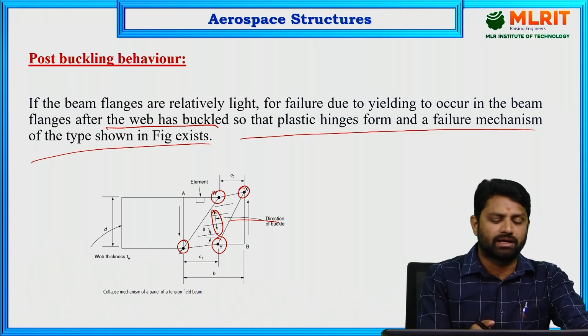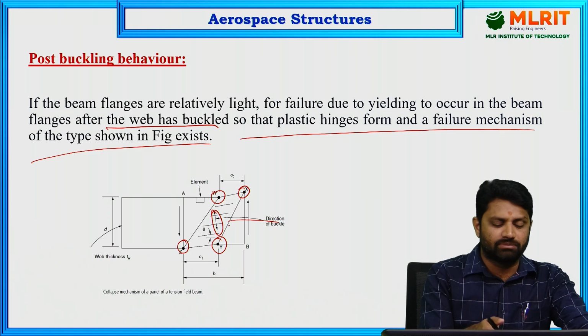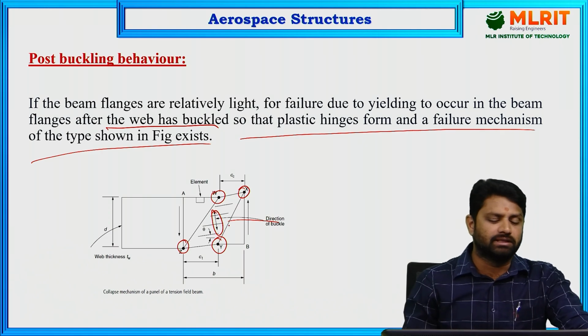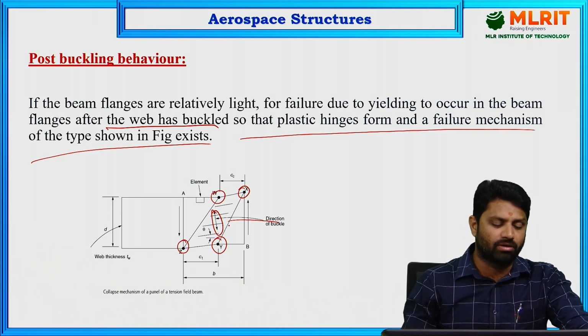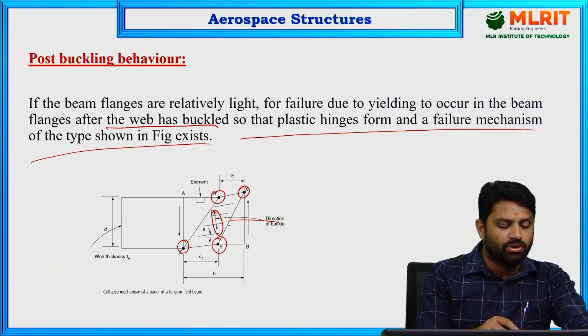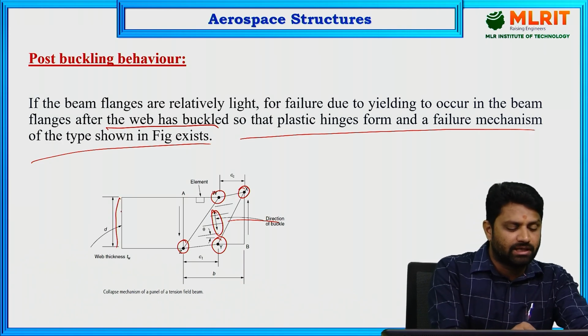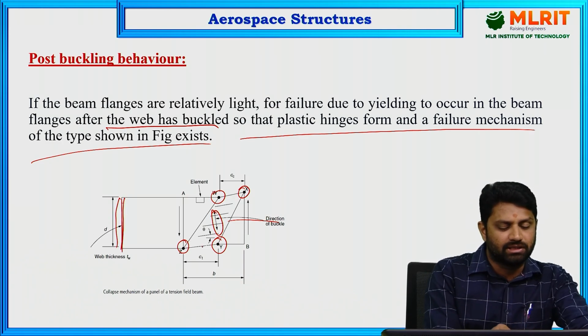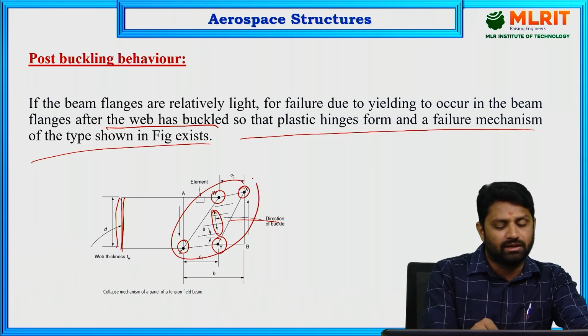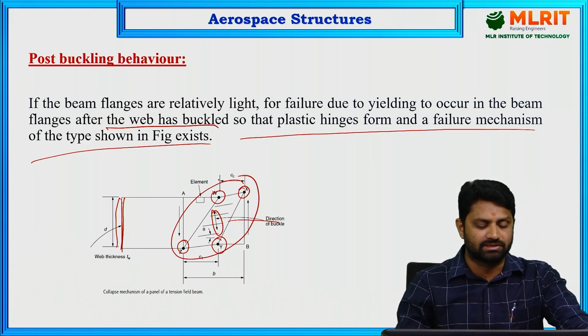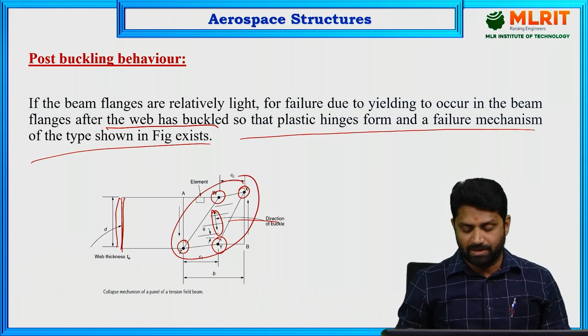After buckling, it has got a particular shape that is shown in this figure, and you can see the plastic hinges that are formed. This is the usual depth of whatever element you consider. Now that is going to be changed to a pattern like this along with the plastic hinges.